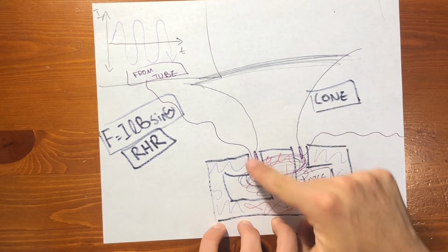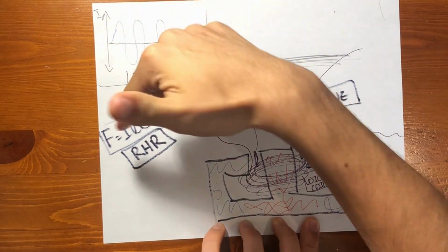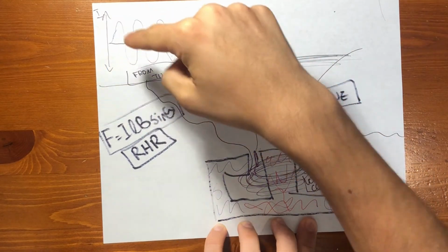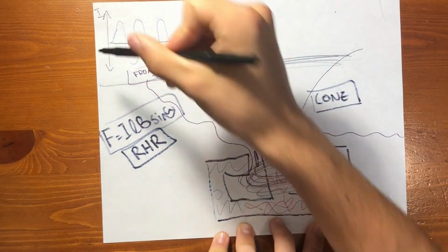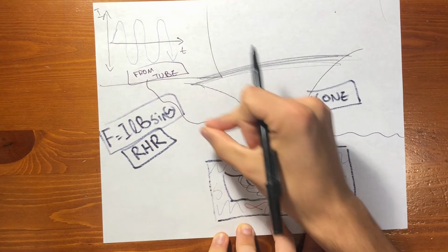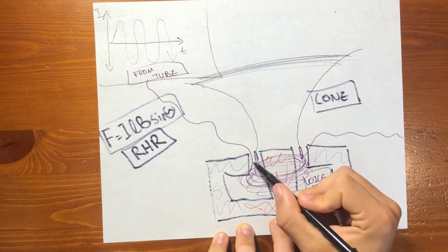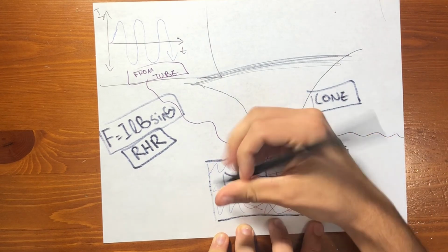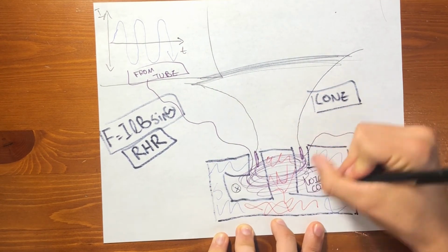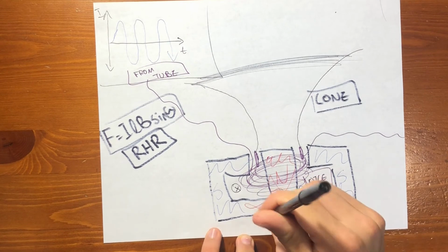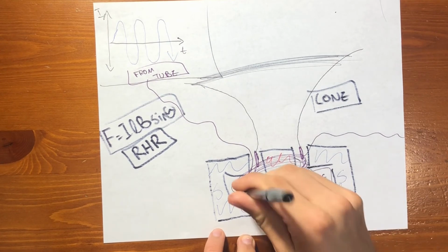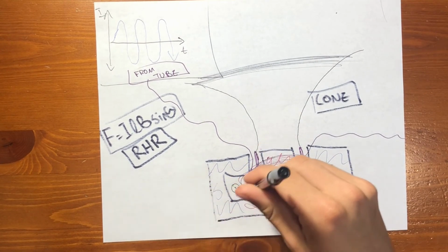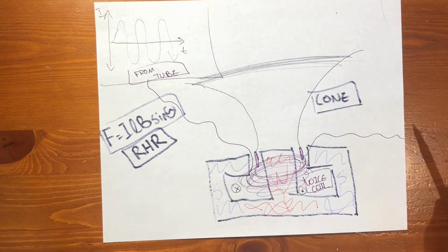So remember that this voice coil is connected to that signal, that alternating current that we send from the tube. All right, let's say that as the current is positive, it's moving this direction. Let's say that it goes around like that. So it goes in over here and it comes out over here. Represent that using X's and dots. Imagine the arrow of a bow and arrow. This is the tail end, right? It has those feathers, and here is the pointy end. Now we can use our right-hand rule to figure out which direction that voice coil will move.